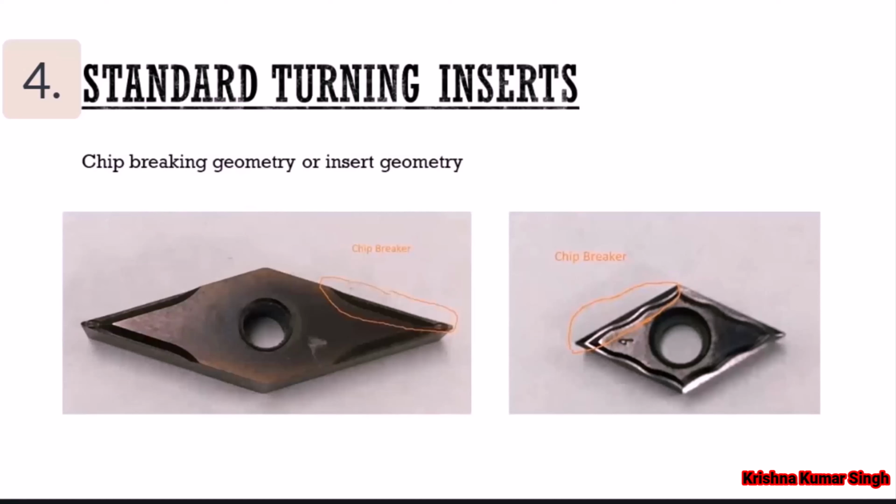However, tool manufacturers also use specific codes for chip breaking geometry and insert grade, which are specific to each manufacturer. Chip breaking geometry, or insert geometry, is the design at the top of the insert used to control chip length. Chip breaking geometries are often specific to certain material groups, such as steel, cast iron, or stainless steel.